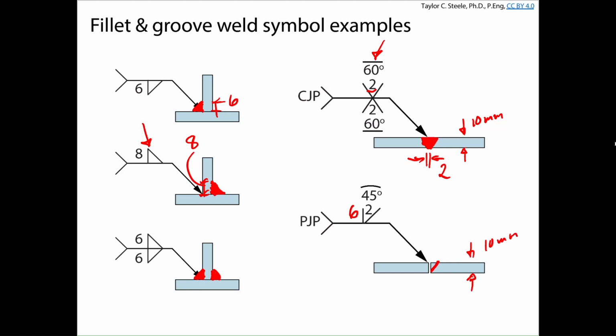Note that with a number, some kind, 6 maybe. Basically what that 6 means is we're only going to weld 6 millimeters of plate, so we might grind it something like that. And then we're only going to partially join. And then this little curve at the top means leave it as convex, bulging out a little bit, so we're not going to grind that weld away.